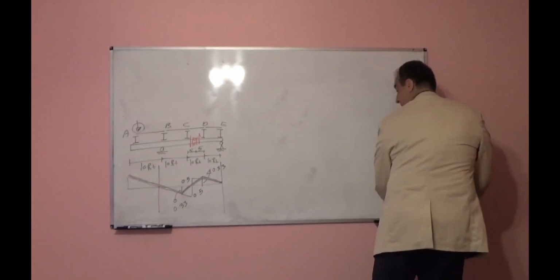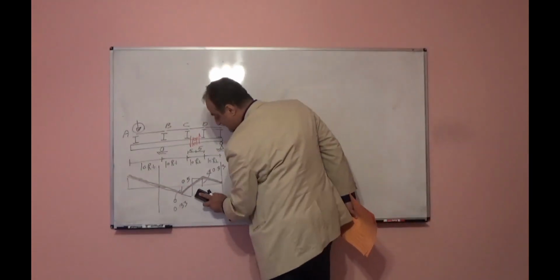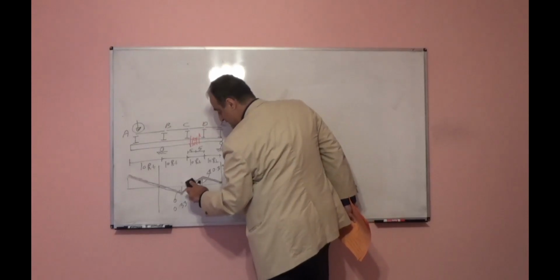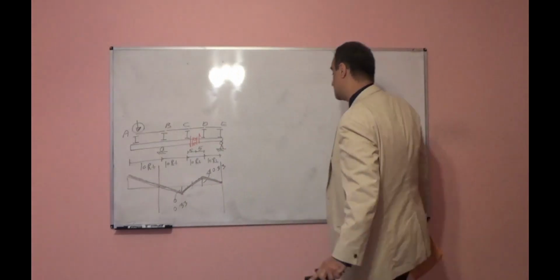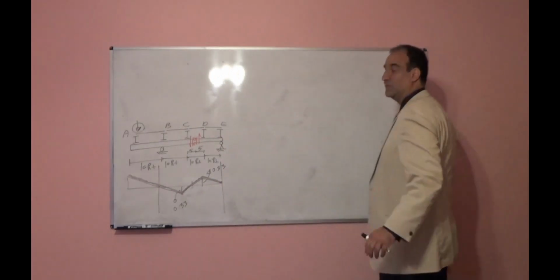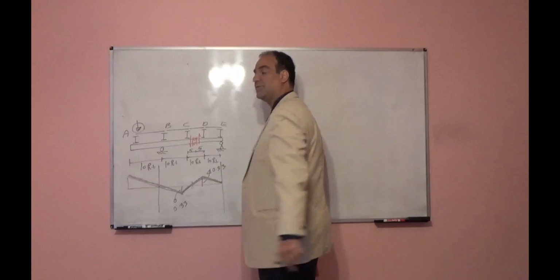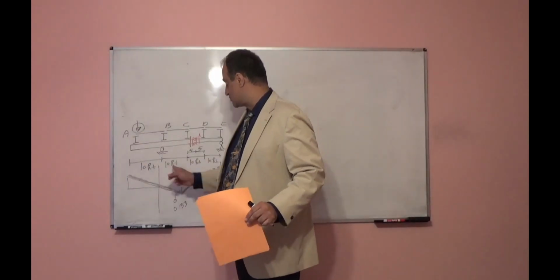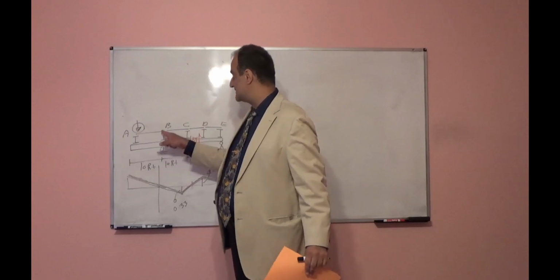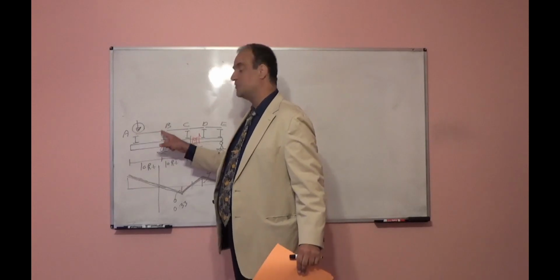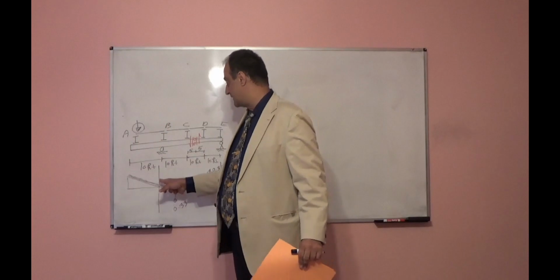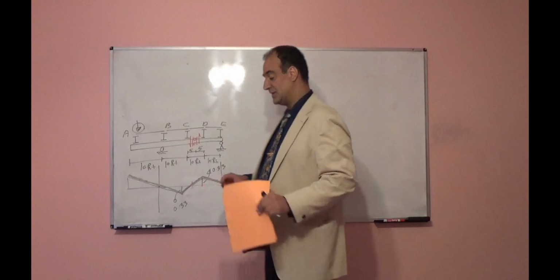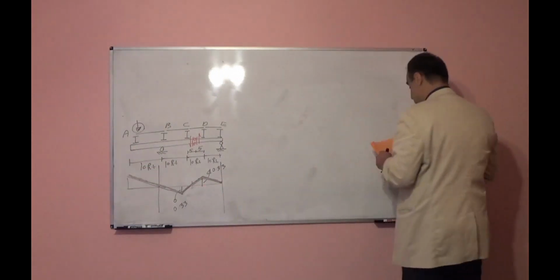You can remove or you can keep this part. This will be the influence line for the girder if we have joists and these kinds of panels. Transfer these points to the influence line, then look at this panel: from A to B, if it is one line, attach one line. If it is continuous from A to C, attach from A to C, and so on. So it is easy to figure out.